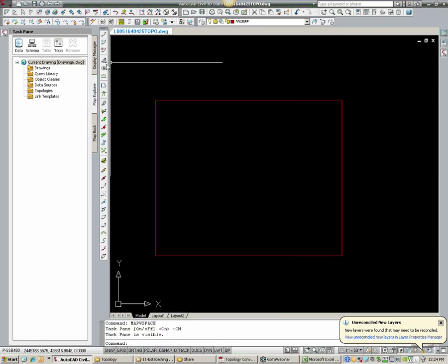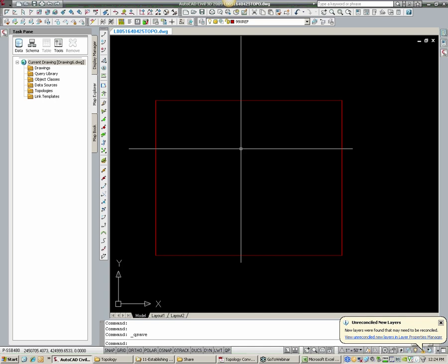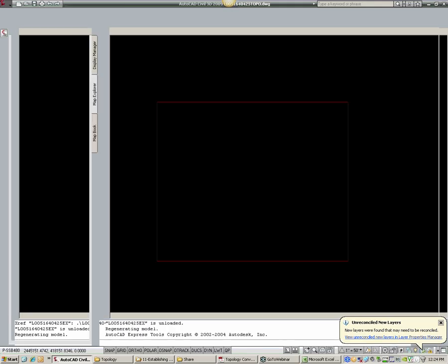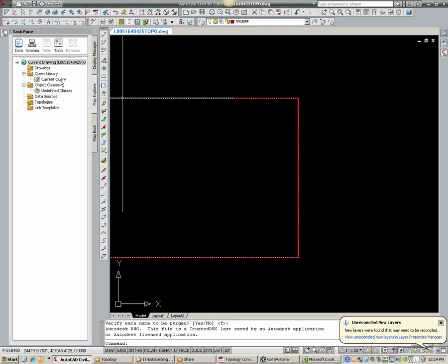All right, so this is the Civil 3D Map task pane, and I've noticed that if you start a brand new drawing, these should have items under them. Just like a lot of other things in this program, if you do a revert, which closes and opens the drawing, then they show up. So you might have to do that, depending on how it feels that day.